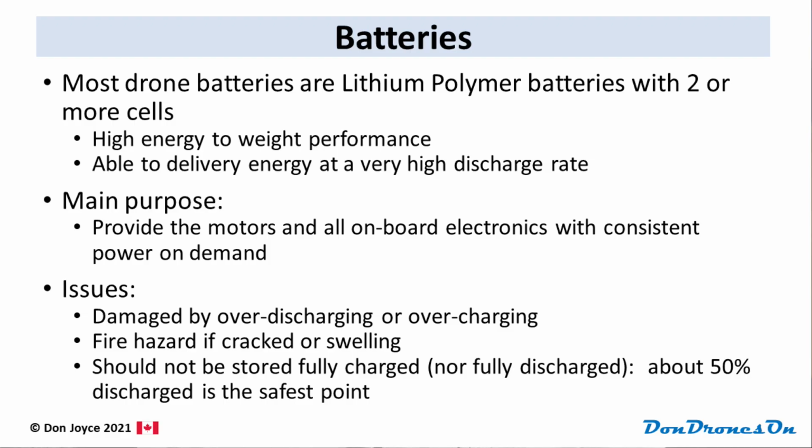Like the saying goes, with great power comes great responsibility. LiPo batteries can be a bit finicky and need to be carefully handled. While they can be charged and recharged many times over the course of their life, if they are discharged or used under load below about 20% of their capacity, then they can be irreversibly damaged. The minimum safe recharge voltage is 3 volts per cell. Similarly, overcharging a LiPo battery can damage the battery and could even catch fire or explode.